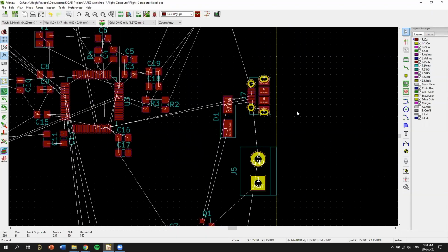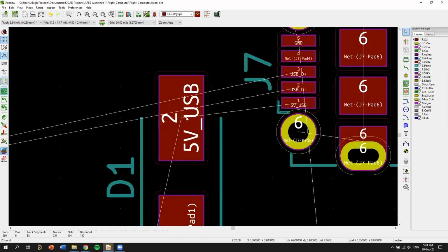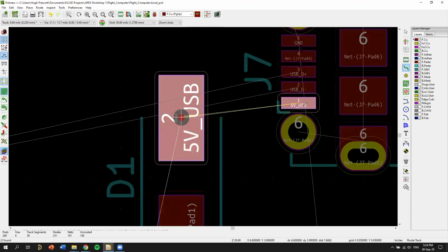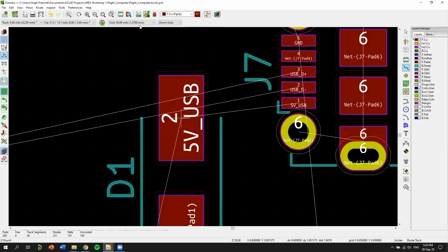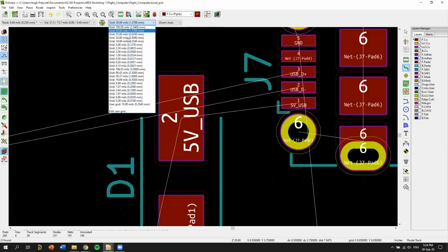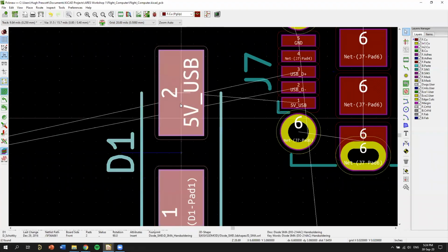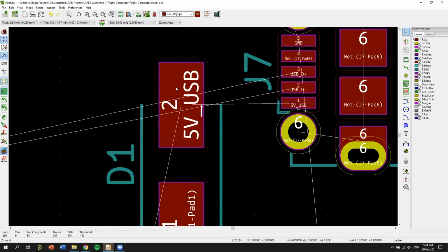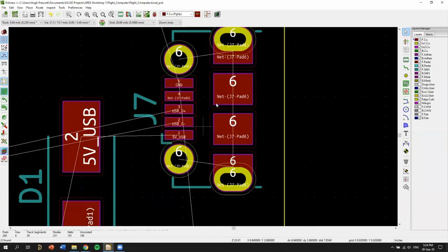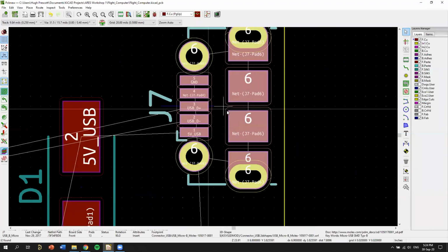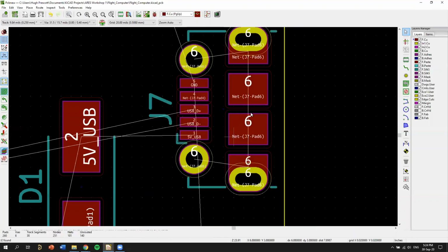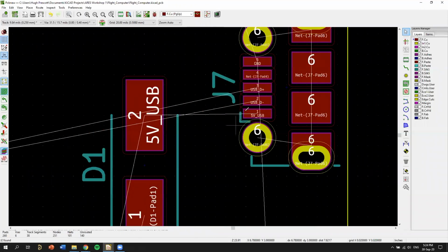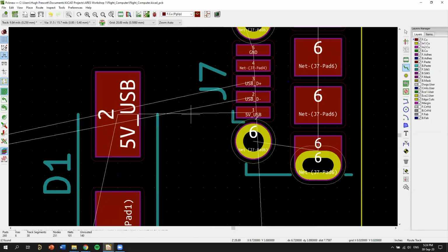And then we can see that we want to connect this 5 volts here to this here. And so I think, if you press Shift X, it'll bring up the routing tool. You just click, and it's good to align things a bit better. So let's do a 20 mil grid. It's a bit straighter. None of these components are on the grid though, which is all right. It's a bit annoying. Boom. All right, cool.